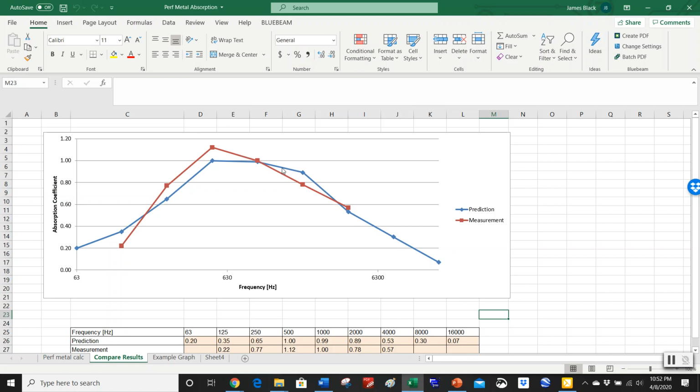So up here, the stuff that's not being absorbed is because it's being reflected back by that protective perforated panel layer. Down here, it's letting everything through, but why this drops off is because of how capable of absorbing the sound the fibrous backer is.